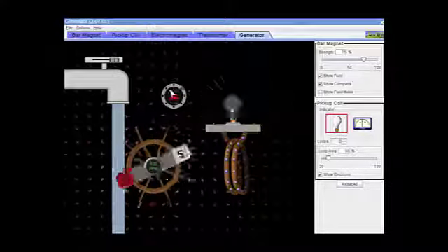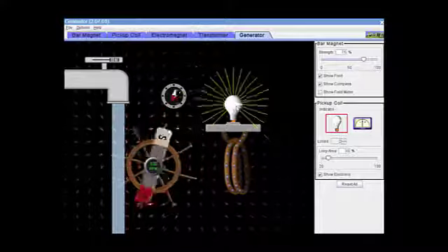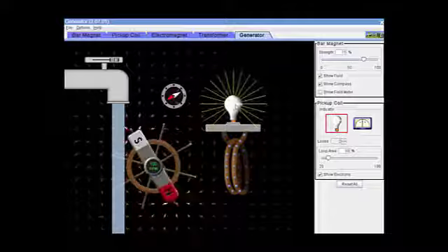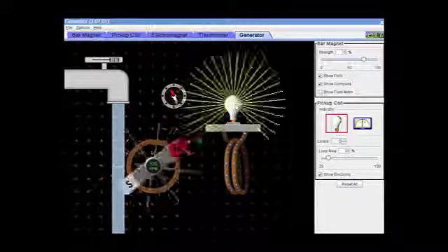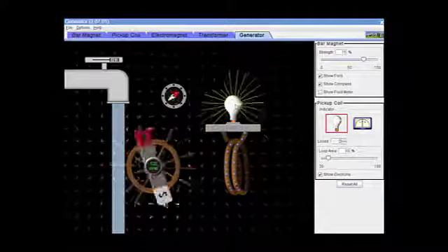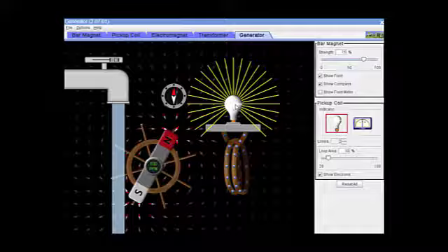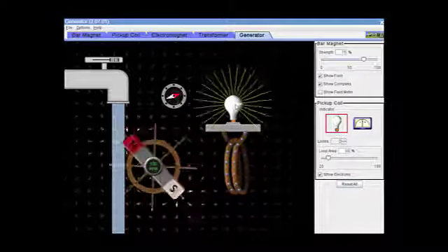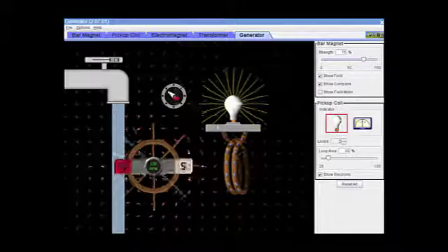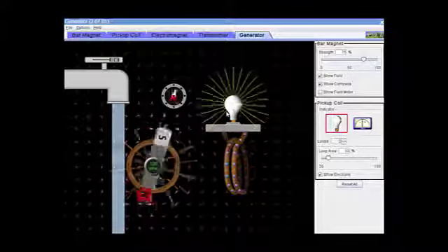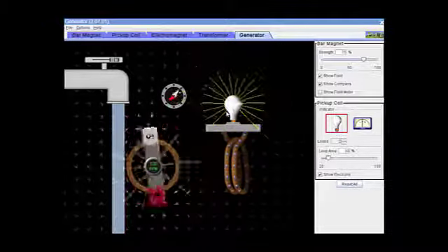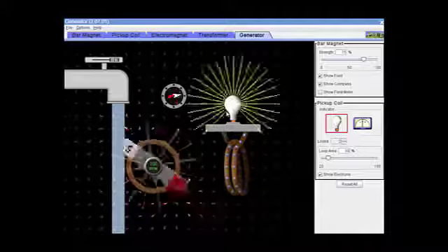And in fact, the bulb really wouldn't be able to cool down to the extent that you would notice it, even if you could catch a change occurring that rapidly. And in actuality, we can create generators that can run at that speed or less and still increase the frequency output by using multiple poles in that generator. So the effects of this brightening and dimming that you're seeing here, variation in the load output, would not be evidenced in most practical applications with a generator.